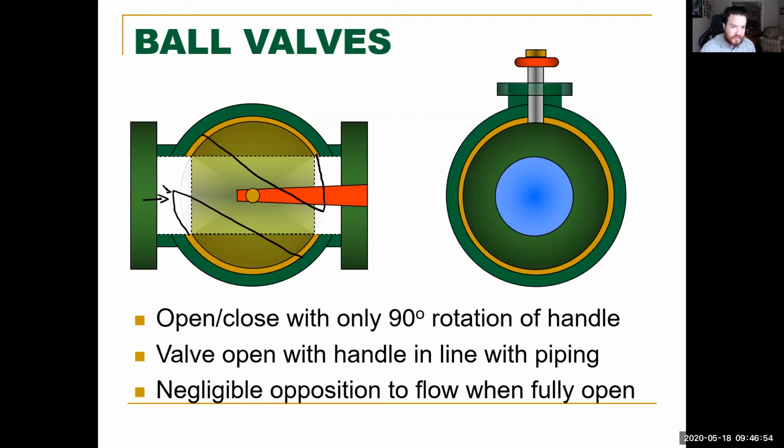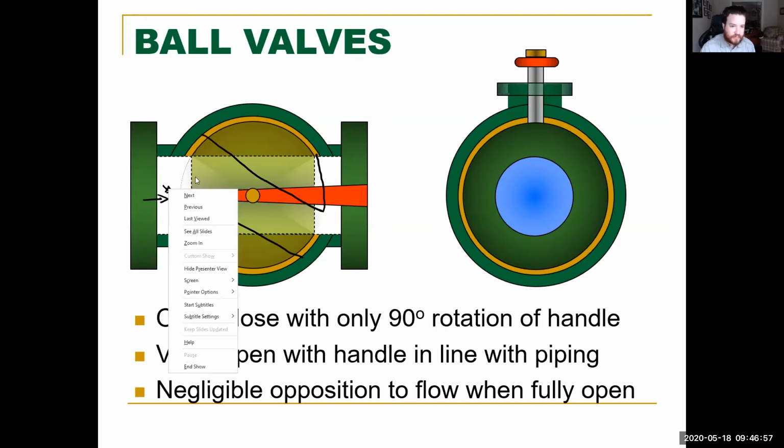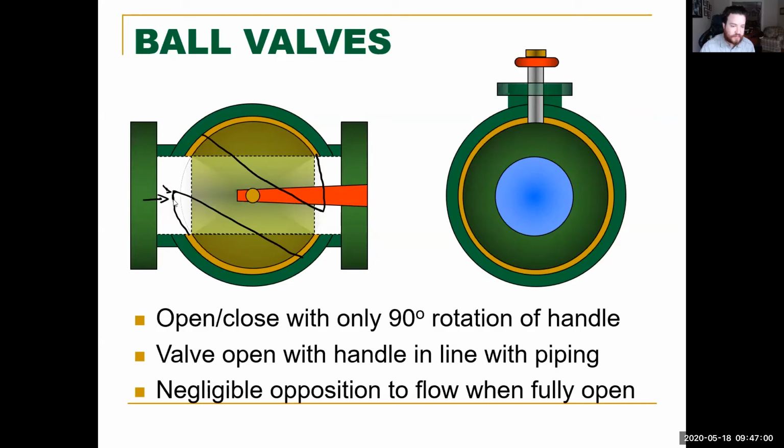And this pointed edge right there will start to round off. And as it starts to round off, you're going to basically give it area when it's fully open or when you need it to be fully closed. Again, it's not going to make the proper seal. And remember, it's not just a 2D shape. It's a circle here, so you're going to be having that problem all the way around it, not just in that one corner.